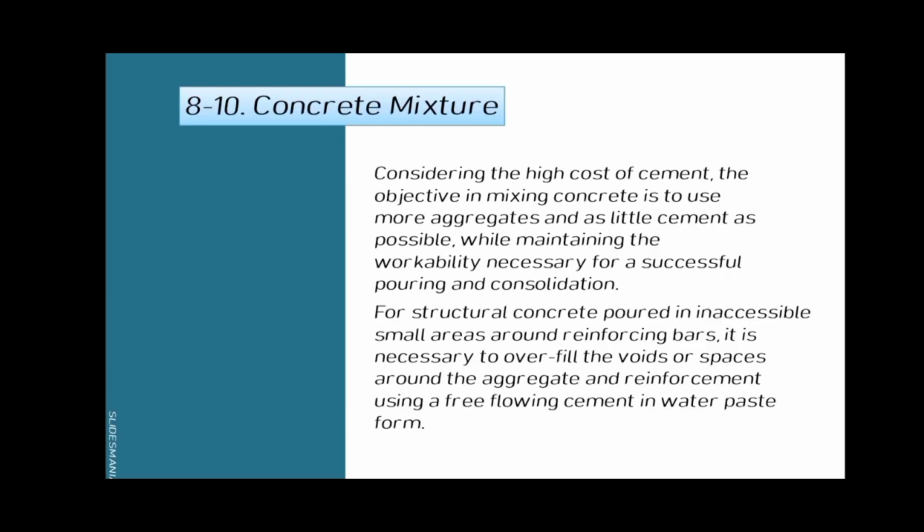Considering the high cost of cement, the objective in mixing concrete is to use more aggregates and as little cement as possible, while maintaining the workability necessary for successful pouring and consolidation. For structural concrete, poured in small accessible areas around reinforcing bars, it is necessary to fill the voids or spaces around the aggregate and reinforcement using a free-flowing cement and water paste.